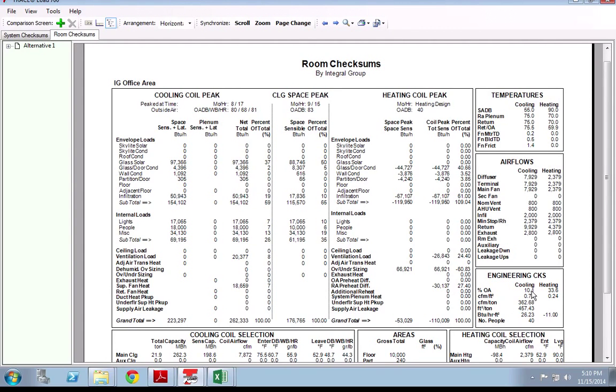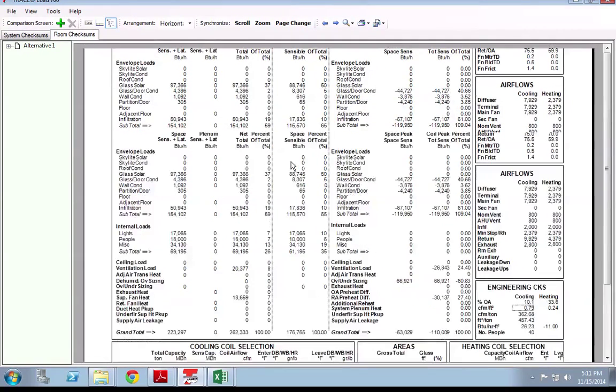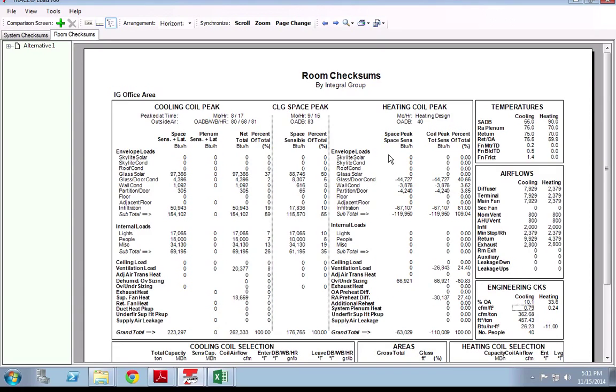The other thing to look at is the percent of outside air and the total airflow density. Again, the amount of airflow density is the same sort of magnitude as the square foot per ton value. So traditionally, we'll see air-based systems be 1 to 1.5 CFM a square foot. Fresh air might be less, around 0.15 to 0.3 CFM a square foot, depending on how much fresh air you're bringing in. Those are some good things to check overall. But generally, I would say the cooling loads here look really spot on for a typical office in our Alameda climate environment.